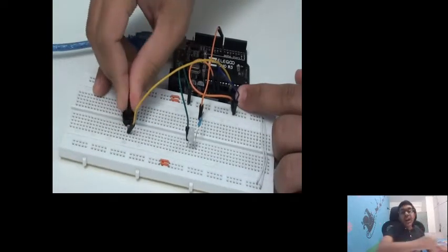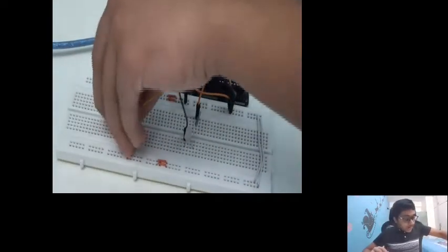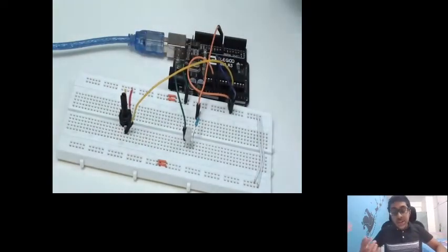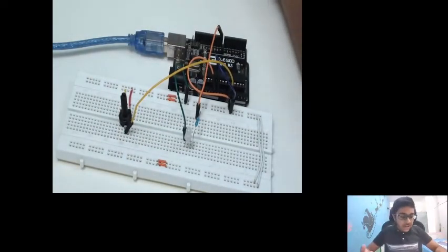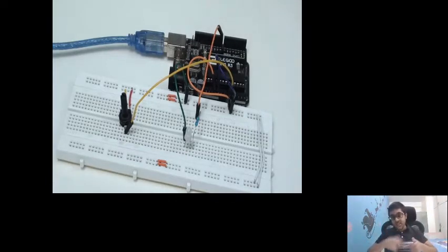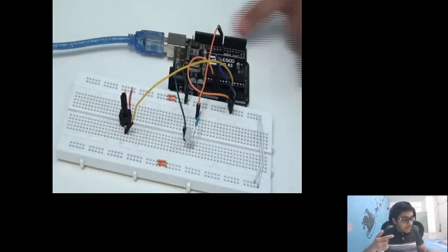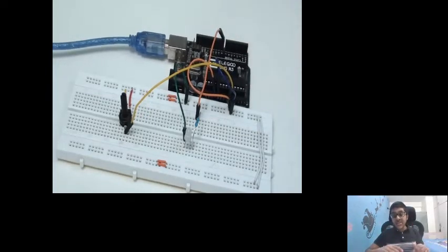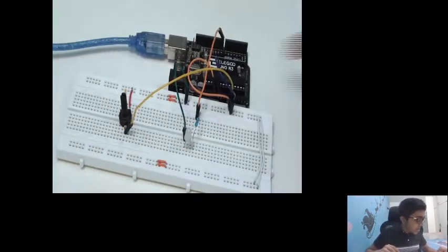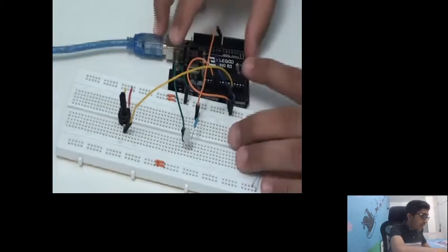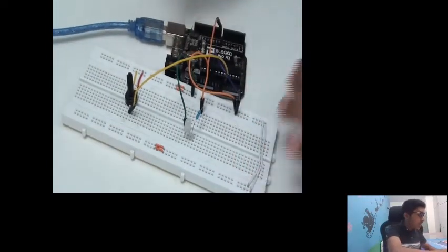That is the idea. Now the Arduino, I should say, has a 10-bit analog to digital converter. That means, what is 2 to the power 10? In binary you can have two values, 0 or 1. So what is 2 to the power 10? It's 1024. You can read a total of 1024 different values on the Arduino. So we just went from two values, binary, 0 or 1, using these digital pins, to 1024 values. That is such a hike in the range. So we can read a lot more values using these analog pins. Okay, now coming to our LED, we do need to make slight changes.